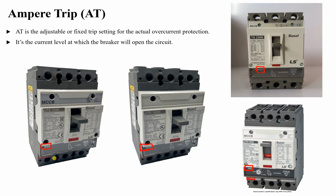So what I mean by this, if we have a circuit breaker like this, it has its own overload characteristics and short circuit characteristics. Now, there are two options here. The first one is that these characteristics are fixed. What I mean by this is that the overload will start at IR, a fixed IR. And also the short circuit, which is magnetic, will start at a certain value called IM.